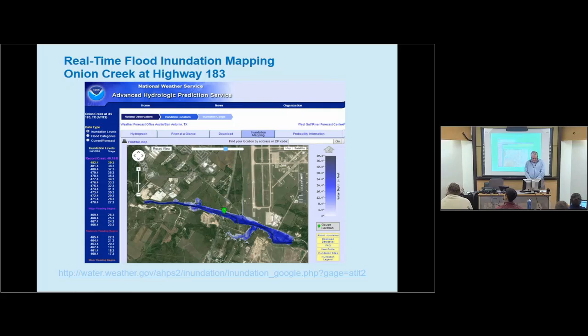that led to the approach that for every grid cell you effectively trace down, and it's part of the D-Infinity tool set. So you trace down, averaging across the multiple flow directions that D-Infinity gives you, till you hit a stream, and you effectively back from that and get the average height that each point is above the stream. So that's the first part of the method, and that allows you to tell, if you've got the depth of water in the stream, where it's going to flood.